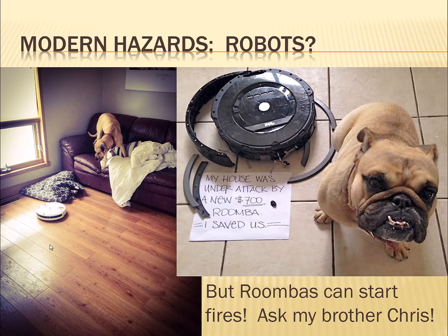Stuff will happen. So this was a weird combination where a halogen light, the old halogen lights that didn't have a proper cover, halogen lights, traditionally the 120 volt style, they get so hot that they can ignite things immediately. It's just like putting a match to gasoline. They light those curtains quickly.